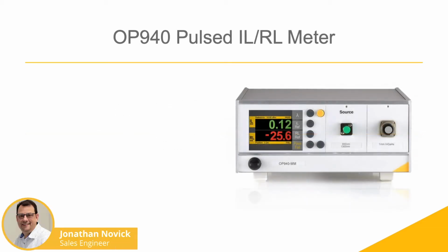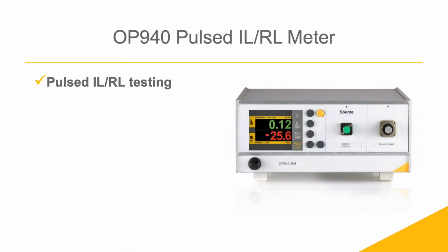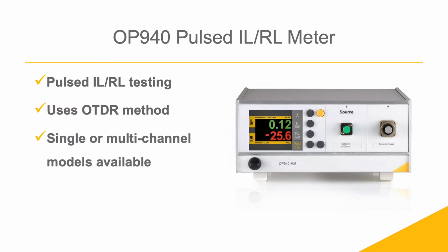The Optotest OP940 uses a pulse technique instead of a CW technique for measuring IL and RL. Pulsed measurements are sometimes referred to as the OTDR, or Optical Time Domain Reflectometer, approach. This model is available in single and multi-channel versions. The pulse method provides a scanning function that is quite handy when diagnosing problems.